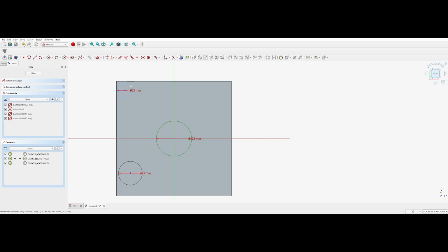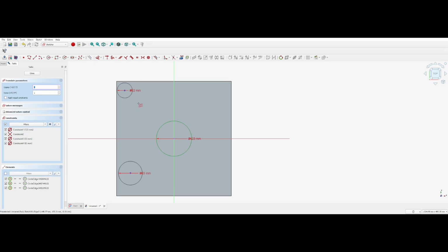If you want them properly spaced, you can select the line or object that you want, or multiples of them, by clicking and dragging. You'll see that they slightly change color. I want just this one, and I want to create copies of it going across the top. So let's go here, which is the move and array. Copying them is creating an array. Now we want to select our movement reference point, which will be the node in the center.